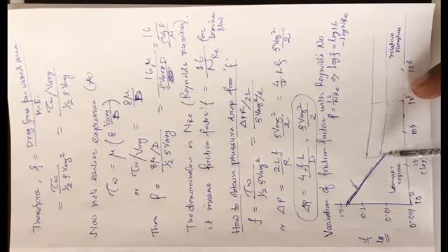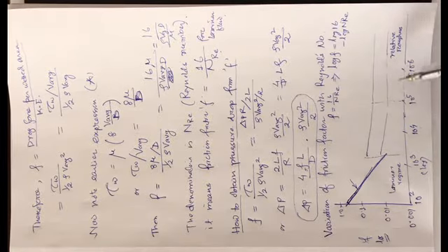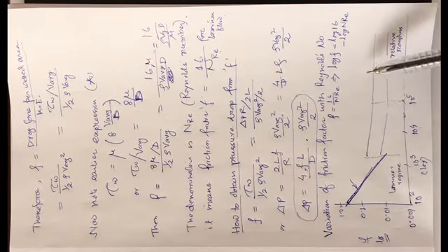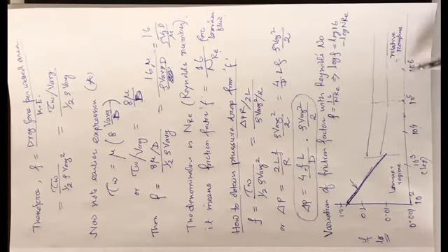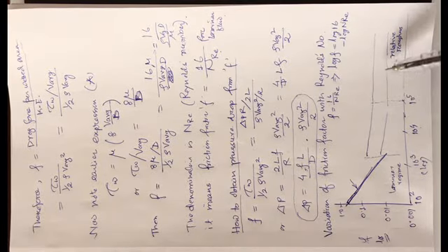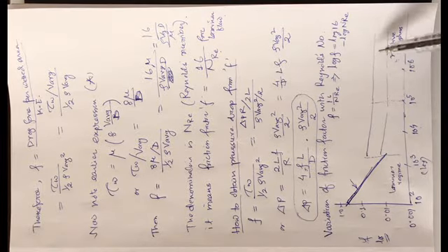So what happens beyond the laminar regime is not apparent from these derivations, but for your understanding you should note that in the turbulent regime the value of F is constant. We can read from handbooks where tabulated values of F are given, which are determined experimentally, and it has been seen that the F value depends not on Reynolds number, rather on the relative roughness of the tube material. You can refer to any standard book and obtain it there.